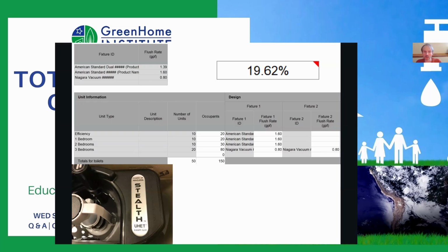They now make super water efficient toilets that work really well, especially with vacuum assisted technology, which should be especially installed in older rehabs with cast iron pipes and long runs to the drains. These ensure that the flush is done more effectively compared to gravity or pressure assist. And I recall in the recent past a lot of pressure assist toilets having lots of recalls and multiple failures across them.